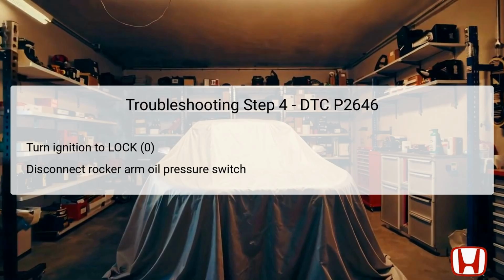The rocker arm oil pressure switch is designed with a 2-pin connector that must be disconnected for further testing. This disconnection enables us to isolate the switch from the rest of the system, allowing for a clearer diagnosis. Once disconnected, it permits verification of switch functionality through direct voltage tests. These steps must be executed carefully to maintain system integrity and ensure accurate readings.